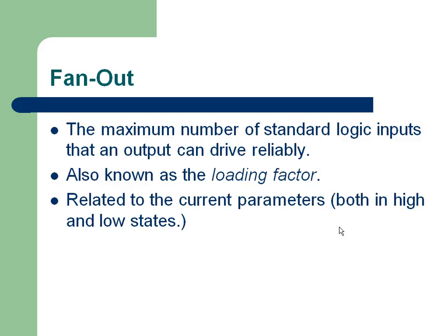Why I am talking about this now is that if you look into FPGAs, it is applicable to ASICs also, but I am going specific to an FPGA example. There is something called a clock buffer, and there are certain units called clock management units, DCM. If you use DCMs, and that clock is distributed to your entire module, your module may be a very big module, maybe 2000 lines of VHDL code, that might be occupying 50% of the chip.